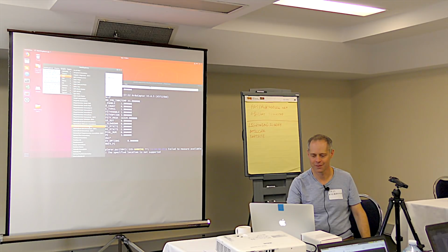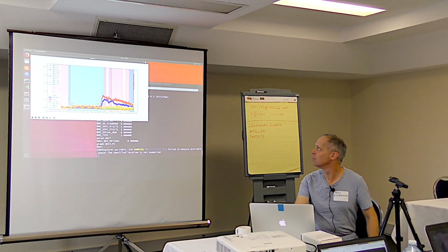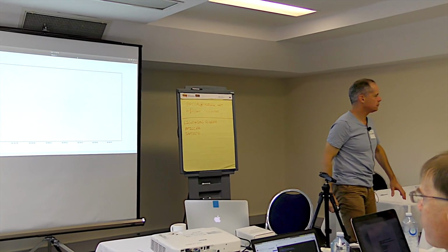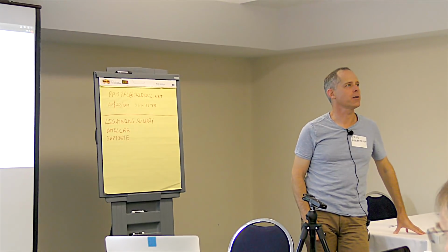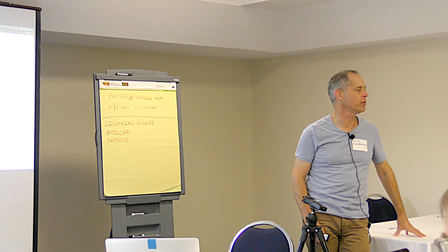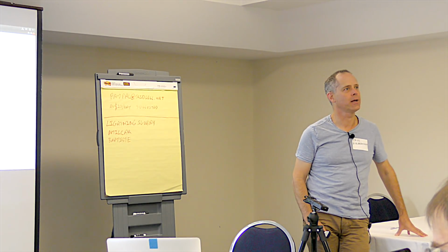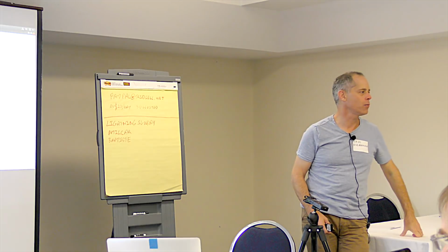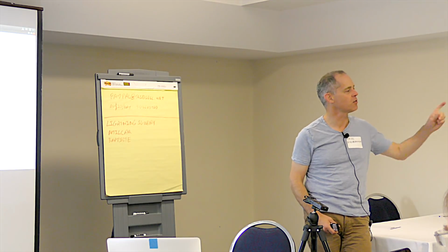Here's a question for you, Paul. With multiple GPS and multiple magnetometers, how's the magnetometer data split up, either in each EKF or among EKFs? No, it's a fallover, right? Yeah, so what the EKF will do is use the first magnetometer instance, the primary instance, and continue to use that. If the magnetometer has been rejected for more than, I can't remember the time period, it will eventually switch over and attempt to use the next magnetometer. And then it just keeps cycling through the list.